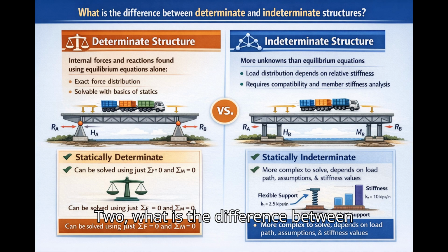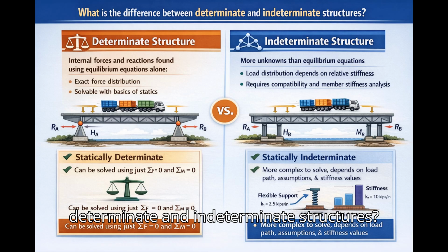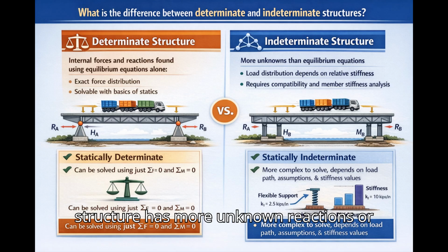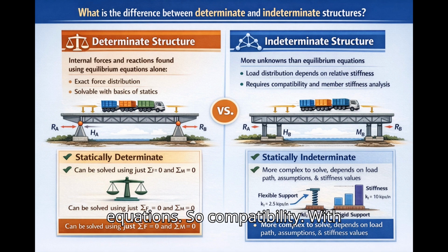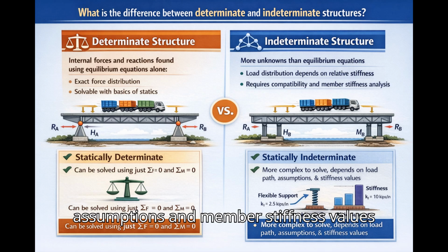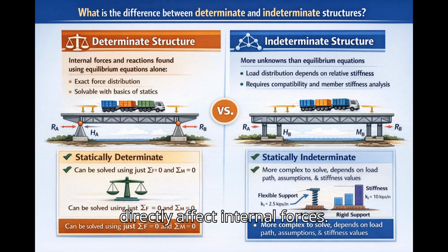2. What is the difference between determinate and indeterminate structures? A statically determinate structure has internal forces and support reactions that can be found using equilibrium equations alone. An indeterminate structure has more unknown reactions or internal forces than equilibrium equations, so compatibility of deformations and member stiffness relationships are required to determine force distribution. In indeterminate structures, load distribution depends on relative stiffness, so modeling assumptions and member stiffness values directly affect internal forces.